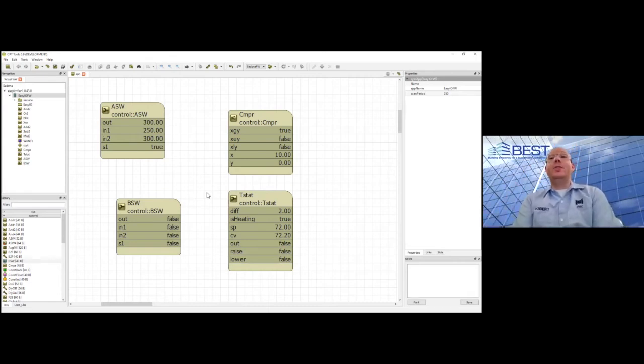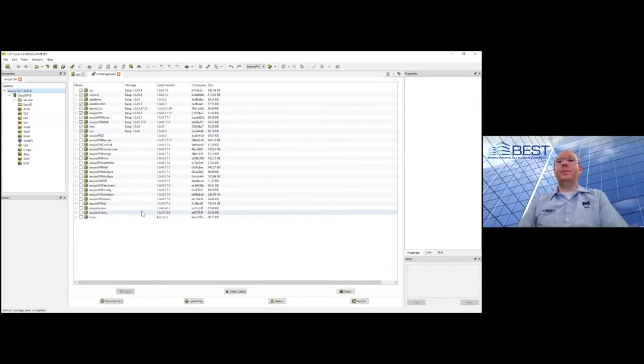So that is a great point, Bob. When you are installing kits, and this was going to come up later, but we'll talk about it now, only install the kits that you need. Because Sedona themselves, not the manufacturer specific, put an upper limit on the amount of space taken up by all of the kits that you install on a controller.